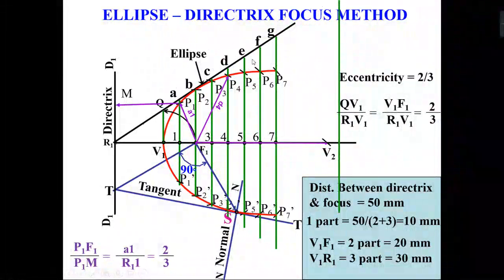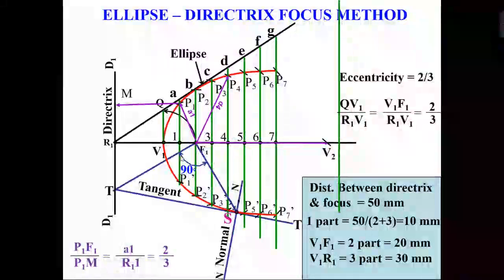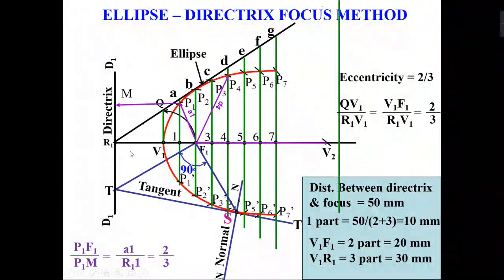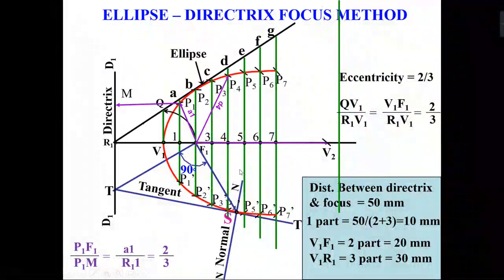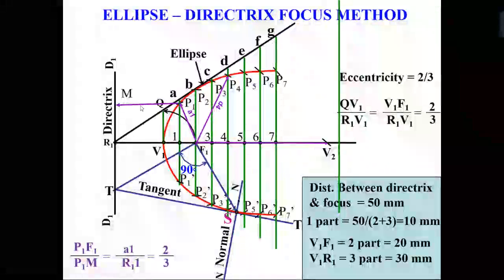So you have to draw all the other things with the help of a 2H pencil, while the ellipse, tangent and normal, and also the axis and directrix, you can draw with the help of an HB pencil. The other things you have to draw with a 2H pencil. So there was another curve, that was the cycloid. How can you draw the cycloid?